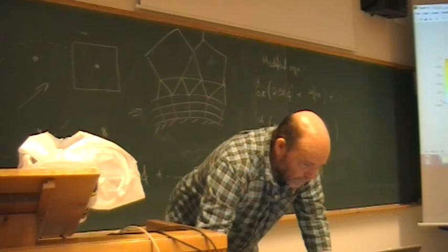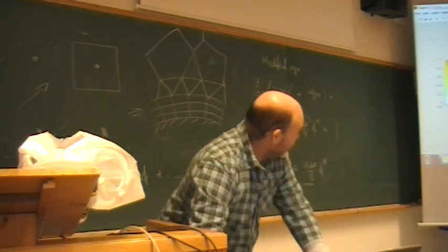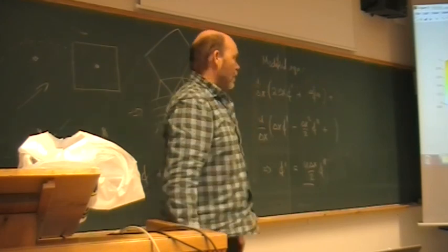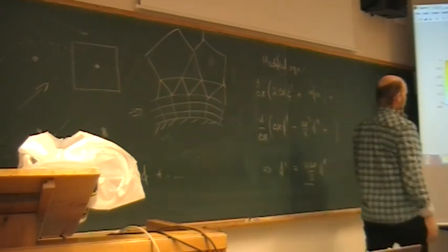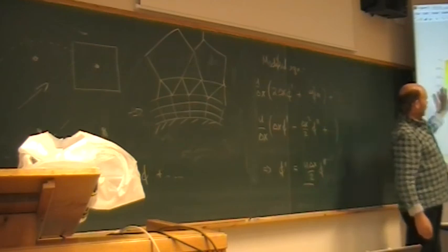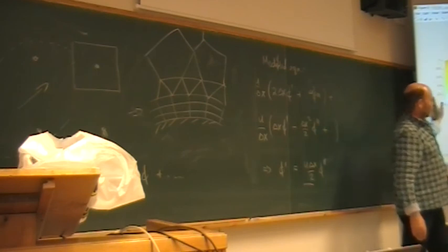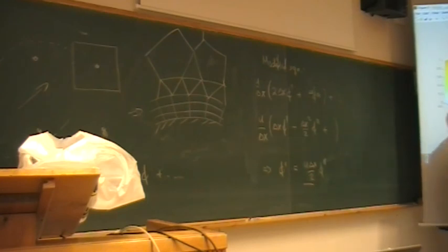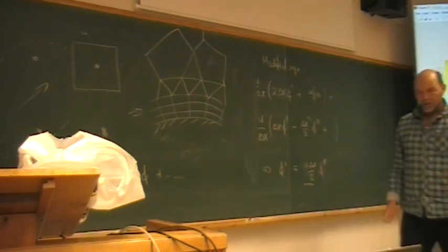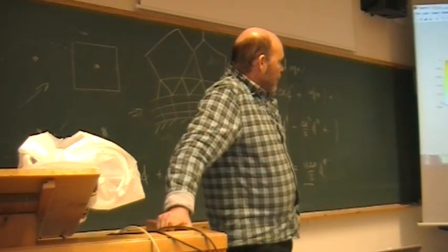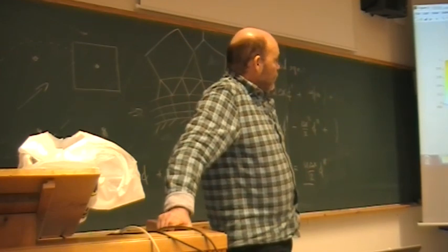It's starting to find a solution here to the left, more or less, and also on the back here, because there we have the Dirichlet boundary condition. We have set this one to be 0 and this one to be 1. So here it can start finding and organizing the solution quite fast. And then that effect will sort of spread out to the domain. And in the end, it will take these two sides here where we have Neumann condition, derivative equal to 0. But still a lot of noise in this picture.